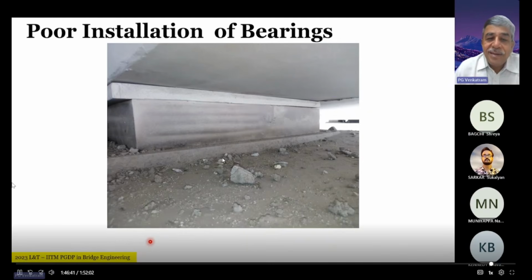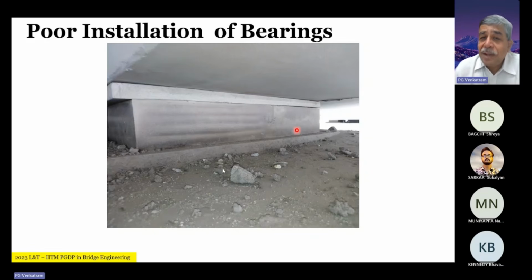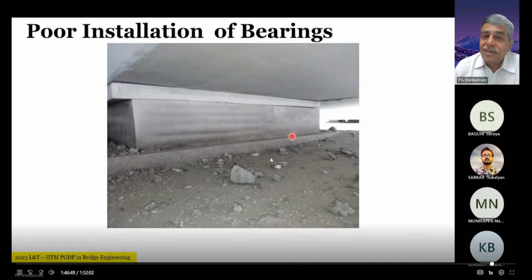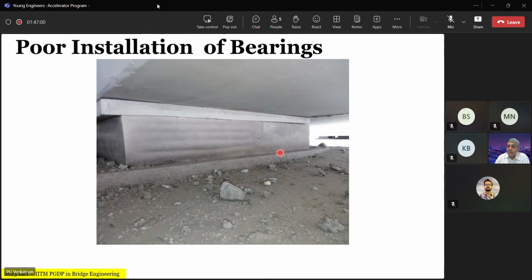Similarly, in an elastomeric bearing, bulging is a presence of load and a lack of bulging is absence of load. You understand? Now the significance of having bulging uniformly all around. Even if I could camouflage this by grouting it after placing the bearing, correct? What does it mean? It means that there is more compressive force here than in this location, which means whatever assumptions you have made for your design of the pier cap, the load positions have all changed. It could be favorable, it could be unfavorable, correct?